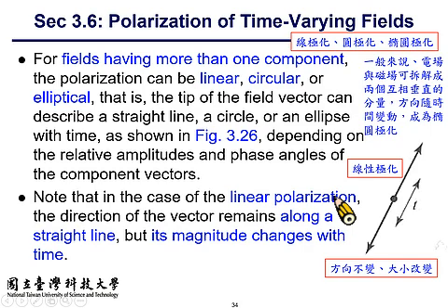All right, so here is an important principle in wireless communication: the transmitting and the receiving antenna need to have the same polarization. If the transmitting antenna is linearly vertically polarized, then your receiving antenna should be vertically polarized as well.